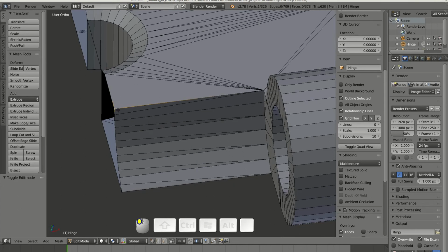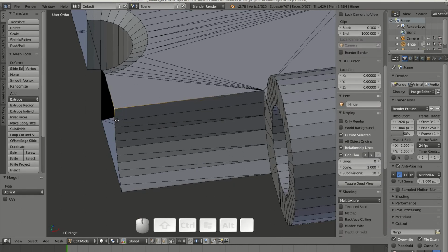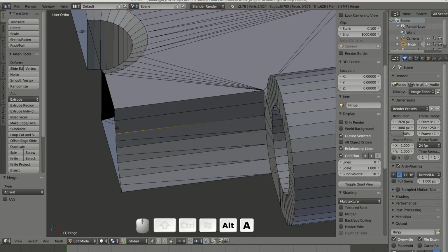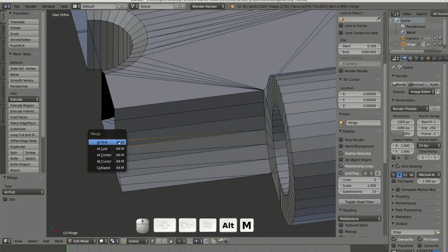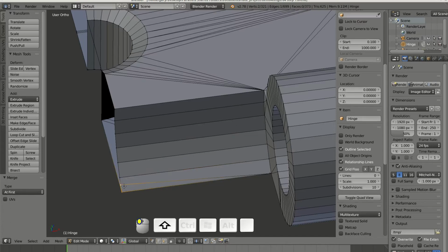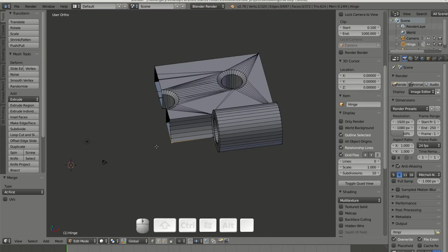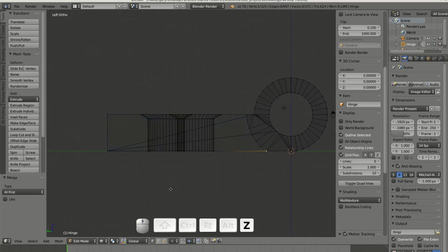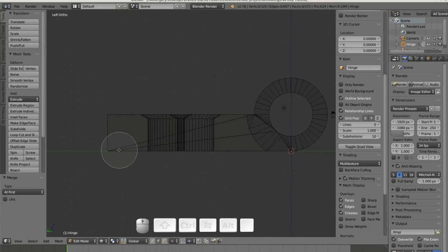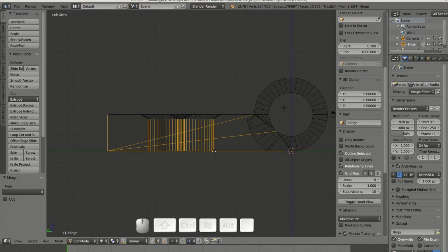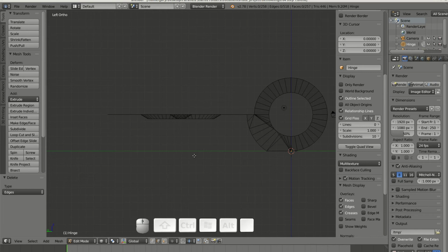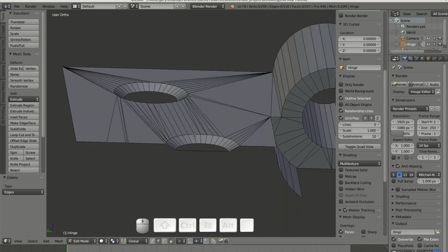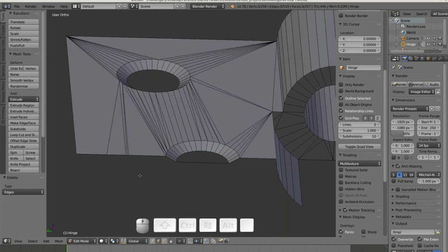I'll do some geometry cleanup on the guide. I simplify the model by deleting the lower edges of the leaf and guide. Many of the top surface edges need to be dissolved.